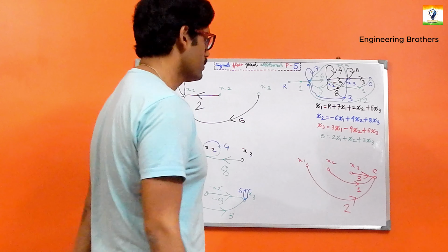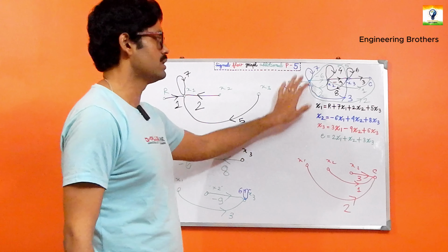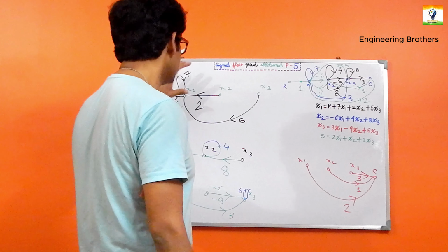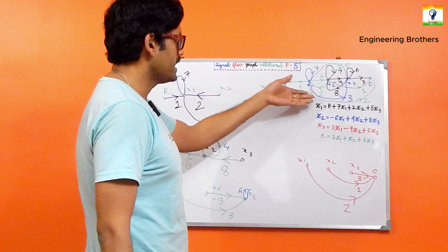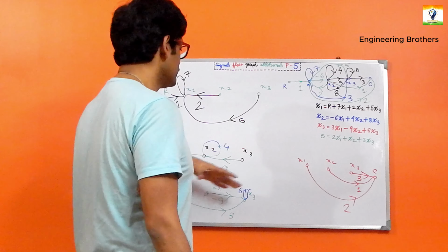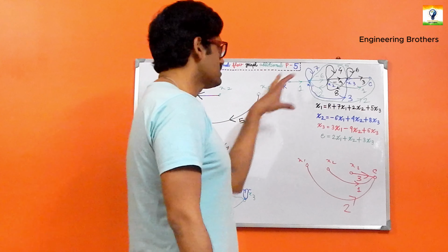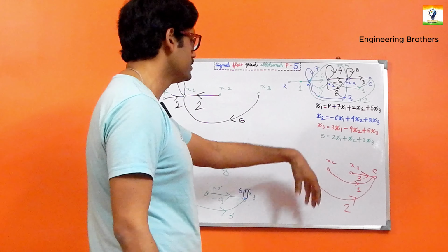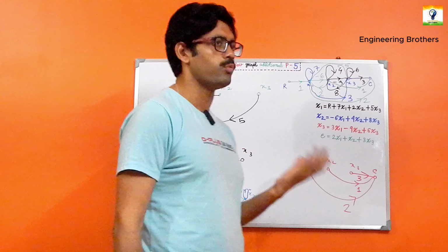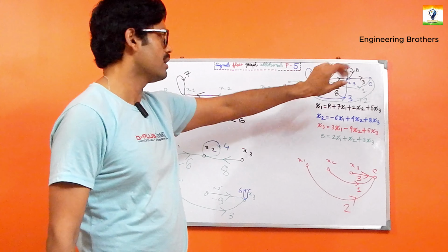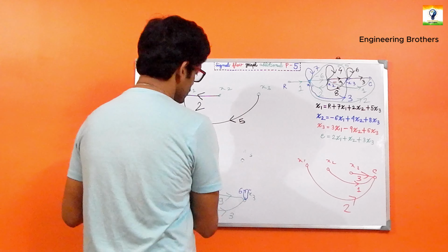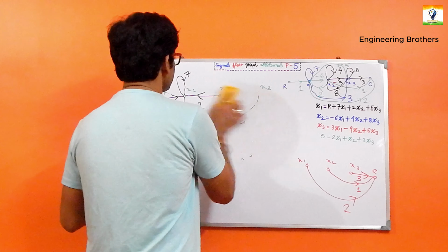I want to repeat this portion once again. First, we have got these four individual equations, and just by looking at them, we formed our individual diagrams. At the last stage we combined these four individual diagrams to have the final signal flow graph. Now in our next point, we should consider this signal flow graph to get the final transfer function. Let us just do that.